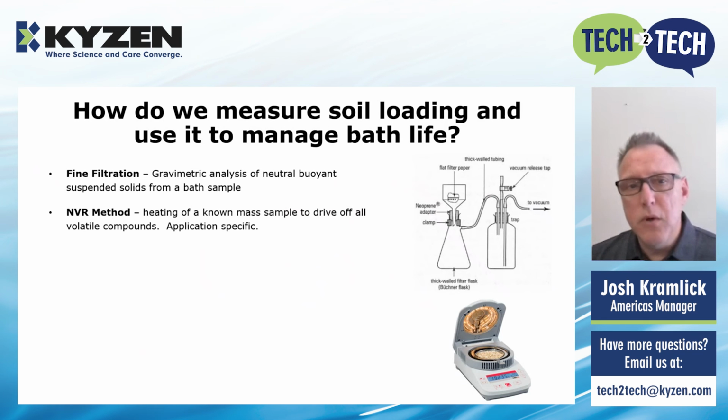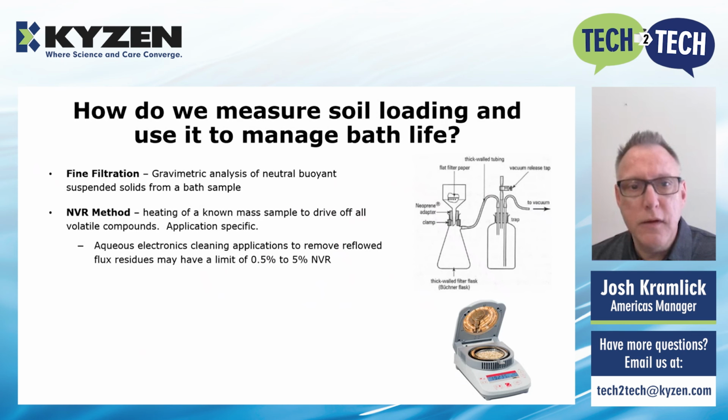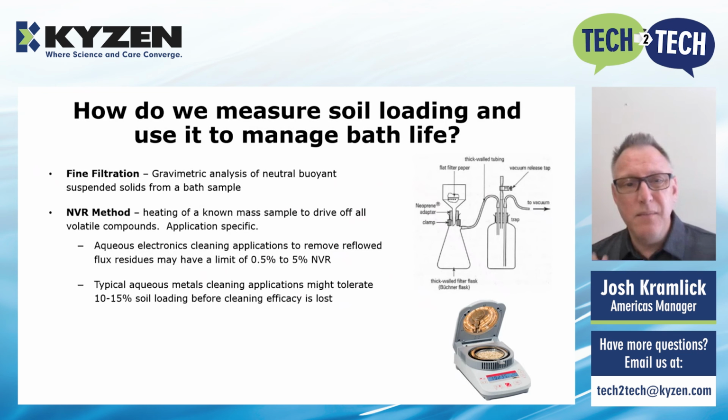NVR method is probably most common in the work that KYZEN does, where we're heating a known sample to drive off volatile compounds, and the exact profiles of those are application specific. Aqueous electronics cleaning applications, for example, where we're removing reflowed flux residues, may have limits of anywhere from 0.5 to 5% NVR. Typical aqueous metals cleaning applications, however, could be as high as 10 to 15% soil loading before we lose cleaning efficacy.